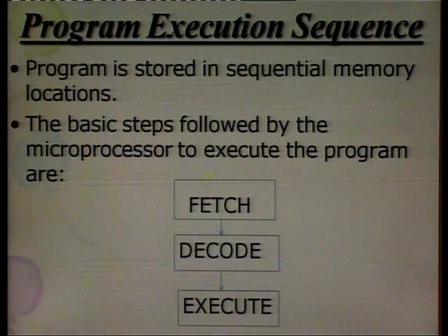Due to this, the lower address lines can now be used as data lines, and due to the 16-bit address which is sent on the address bus, any one memory location out of the total memory is selected where we have stored our program or our instruction.